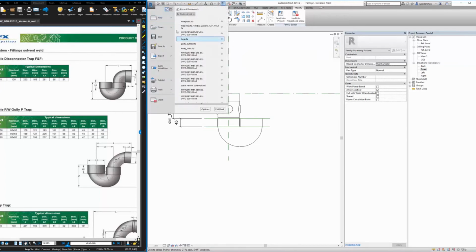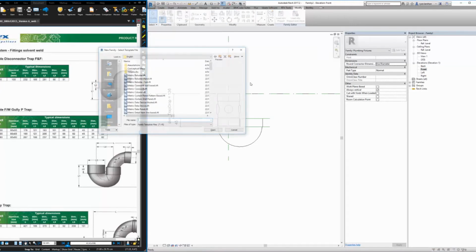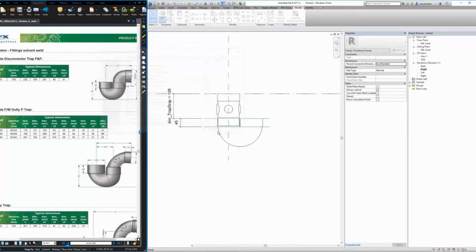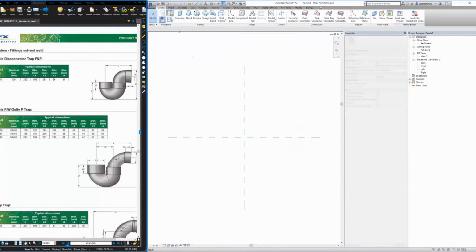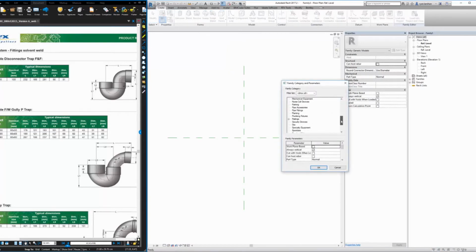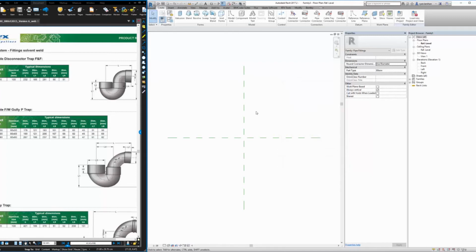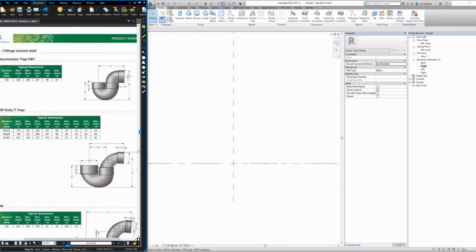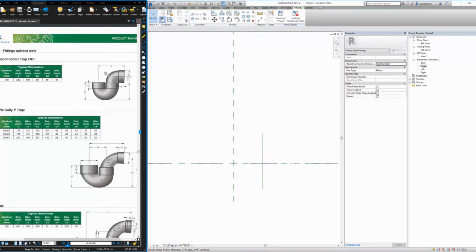And then what we're going to get to now is we're going to create the last part of the trap, which is the outlet. Now, you might be thinking, well, Ryan, why have you made this floor waste as 3 separate parts? Well, that's the exciting bit for a hydraulics guy. What we're doing is we're making this as 3 separate parts, so then we can rotate the four-way riser and the outlet individually to the rest of the trap.